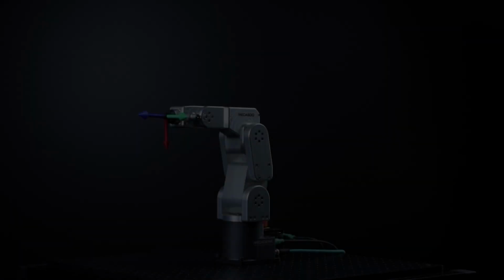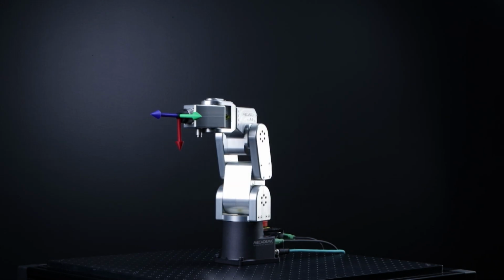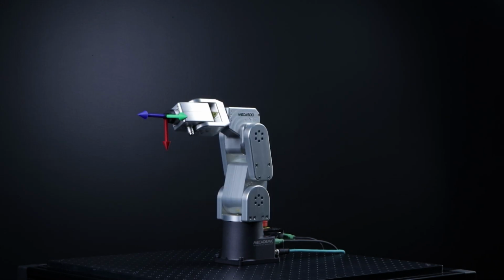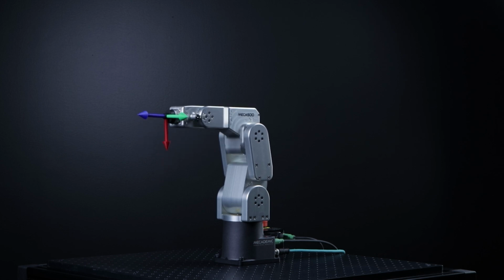All in all, Cartesian moves can be thought of as a series of very small joint movements that cause the end effector to move in a specific path. The following commands can be used. The arguments of movelin are the target pose of the TRF with respect to the WRF. With movelin, the origin of the tool reference frame, i.e., the TCP, tool center point, moves along a straight line.